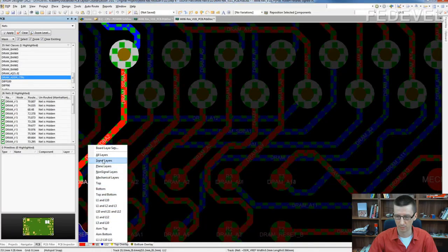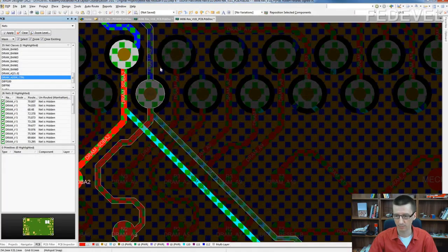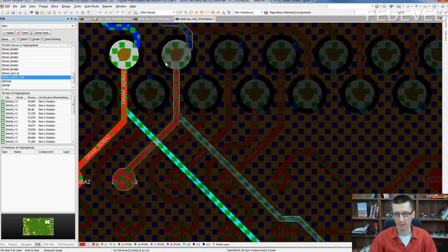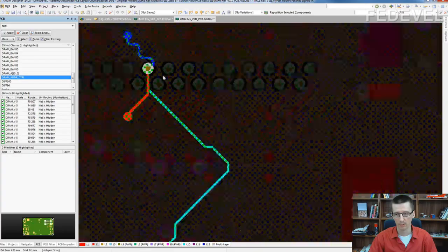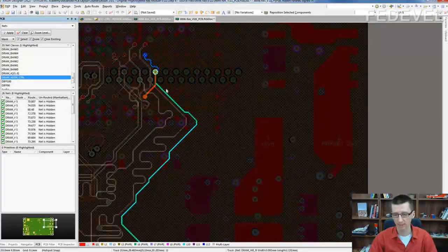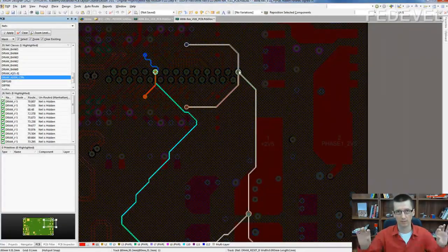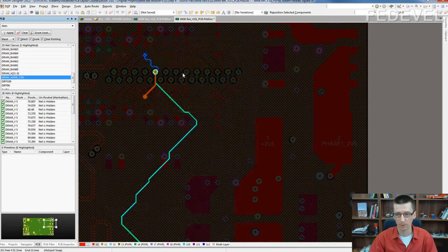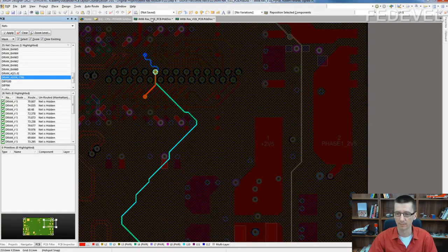If you have a look, this is a plane, see? Here we can nicely see it flows between the through-hole vias. If you place them very close, you will have a big cut under the memory chip, a big cut in ground, a big cut in all the power planes. You don't want to have this. You really want to flow the copper between the through-hole vias.